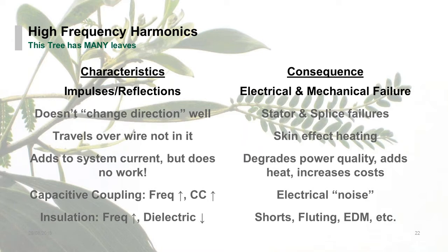As I said earlier, you can create torques inside the motors, you can damage bearings, and then you can also attack insulation and things of that nature within the motors as well. So you'll have shorts, usually on end turns and at splices or near splices. But if you get to really long cable lengths, like in the case of an electric submersible pump, where you can have surface cabling in the miles, and then downhole cable, which in our applications is about a 1/4 mile, but can be up to 10,000 feet or more in the oil fields.